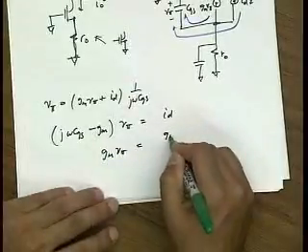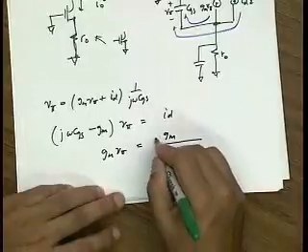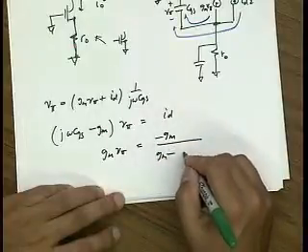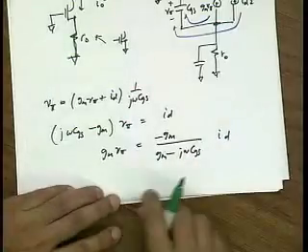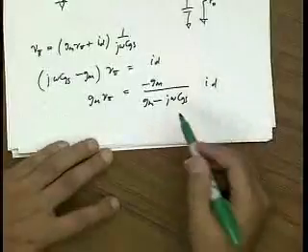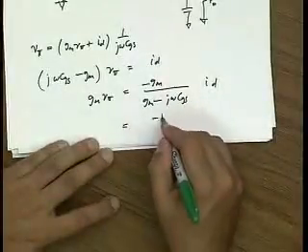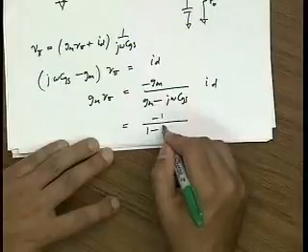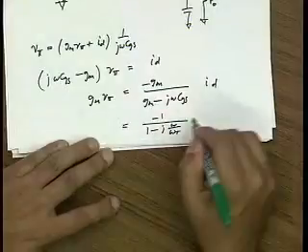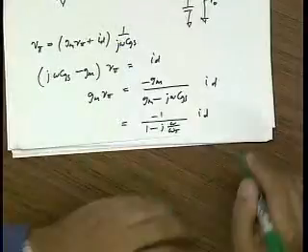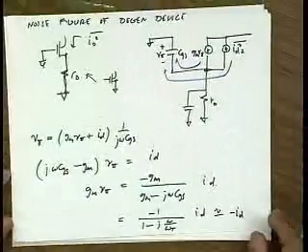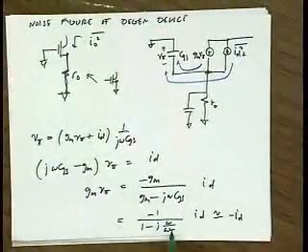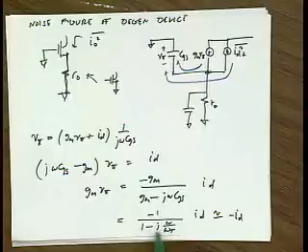GM V pi is GM divided by minus GM minus j omega CGS times I drain. Or if I divide numerator and denominator by GM, I get minus 1 minus j omega over omega t. And so this is approximately minus I drain at low frequencies. So what I've just shown you is that if frequency omega is much less than omega t, this term goes away, this is minus 1, and therefore